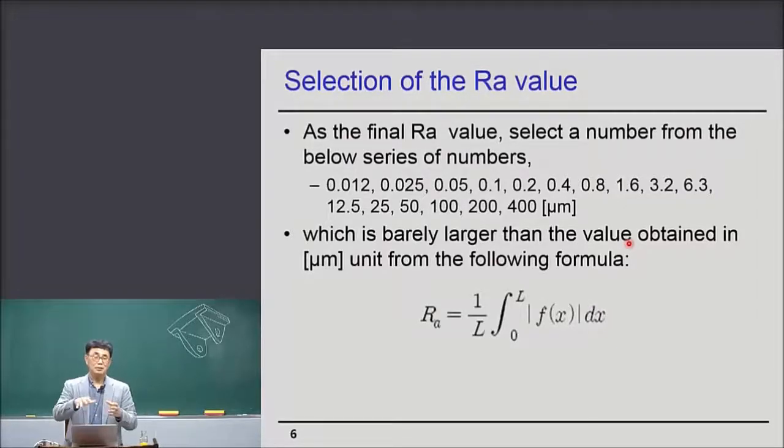Then the surface roughness of the plane you'd like to measure, we call it 1.6 Ra, 1.6 micron Ra, okay?